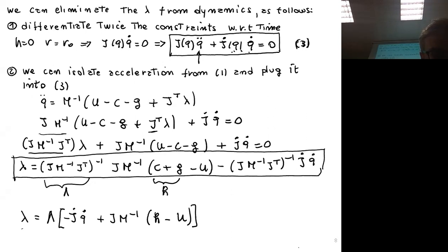And we see that the contact force depends both on the state, also on the mass, the Jacobian depends on the position state, but also on the torques. So in rigid contact, we see whatever we saw in the simple example, that the external force will depend on Fx, the commanded force. In this case, it will depend on the commanded torques.